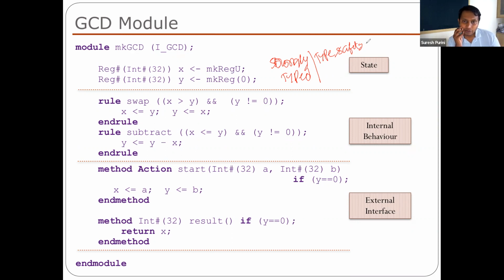So imagine you generate a design, your synthesis takes 2 days, and then you try to put it in the hardware, and then you see some bug, or at emulation time you see some bug. Emulation time, okay, I think it doesn't take much time, but after synthesis it takes a lot of time. So you want to catch the bugs early on in the development cycle.